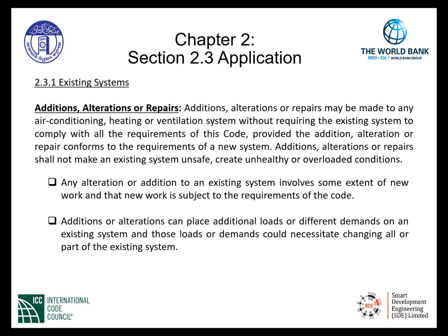As code users, we must understand that the existing systems have the right to exist, provided they have been maintained as originally designed and function accordingly, as we saw in the last slide. However, if we decide to provide any alteration or an addition to an existing system, it involves some extent of new work, then the new work is subject to the requirements of this code.